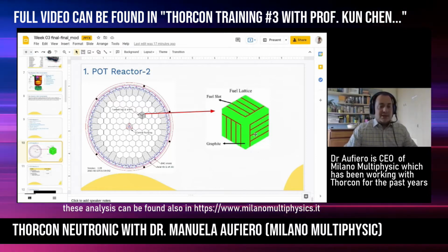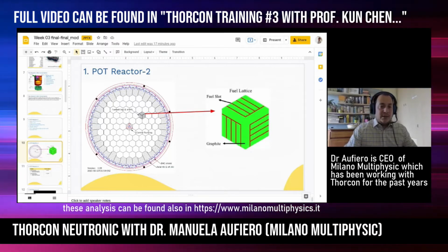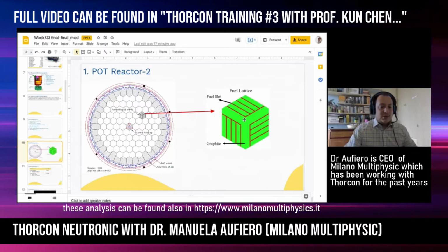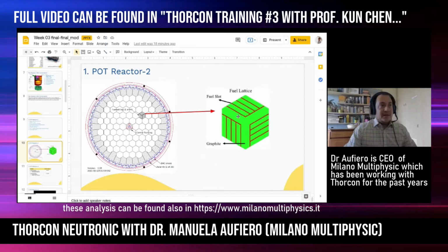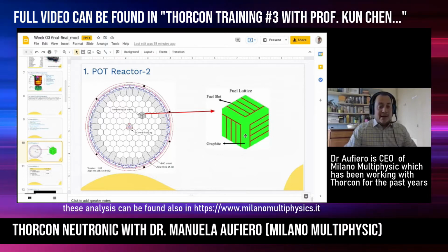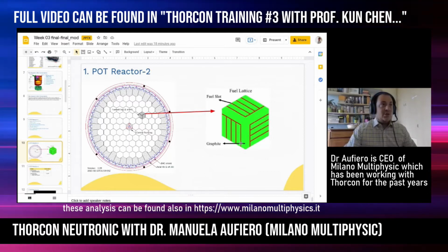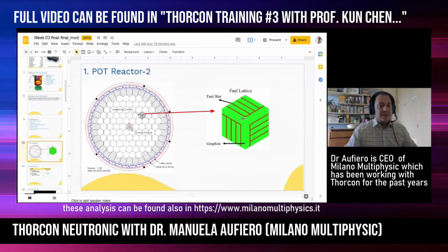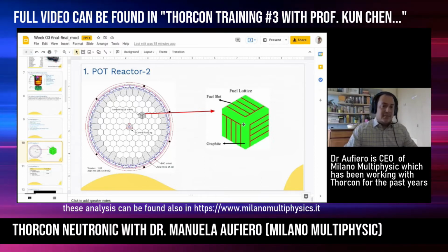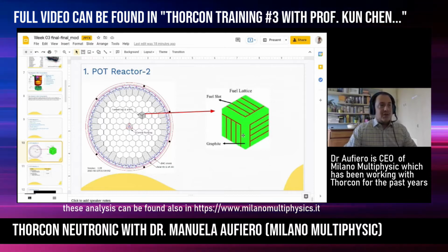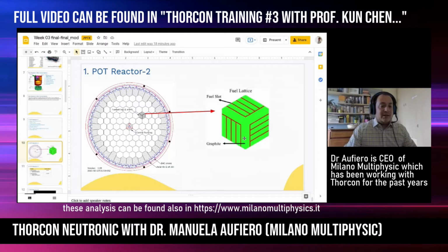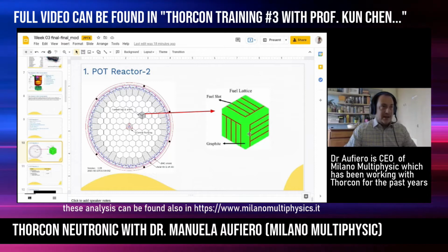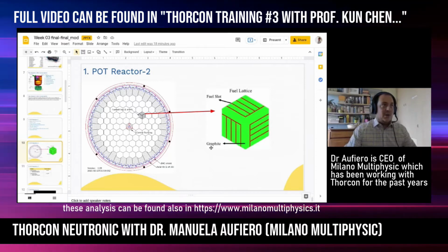The fuel is heated through its path along the 3-4 meter slugs from bottom to top, and reaches the maximum temperature. It is heated mainly due to fission, and graphite is also heated by gamma and neutron irradiation. So the salt, which is the fuel, also acts as the main coolant for the graphite. A variable fraction of the heat, let's say around 5%, is released in the graphite. The temperature of graphite increases the irradiation damage due to neutrons at high energy, so we are interested in keeping low graphite temperatures.